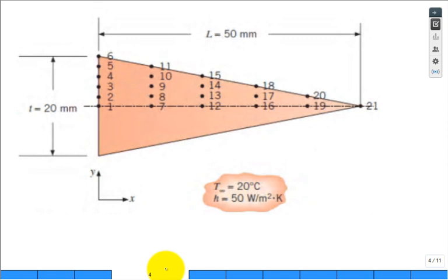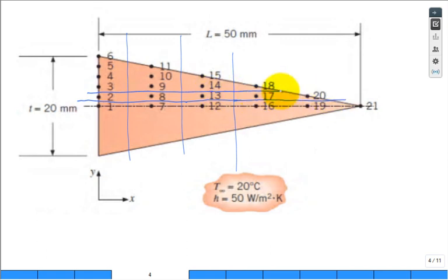All right, so what I was asking you to do is discretize it. So basically, halfway between the sets of nodes, put in a dividing line, and likewise a horizontal dividing line, and where they intersect are going to be the corners of the control volumes or control areas for each node. And so this one goes through like that. It goes all the way across and all the way across. I see some of you have straight edges, and that makes it very accurate. If you draw it accurately, it's a lot better. And then this one goes down and down.